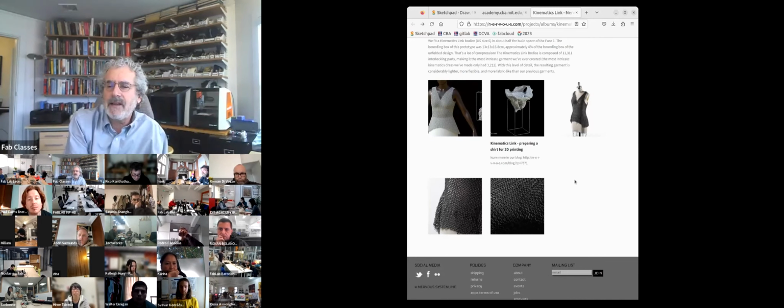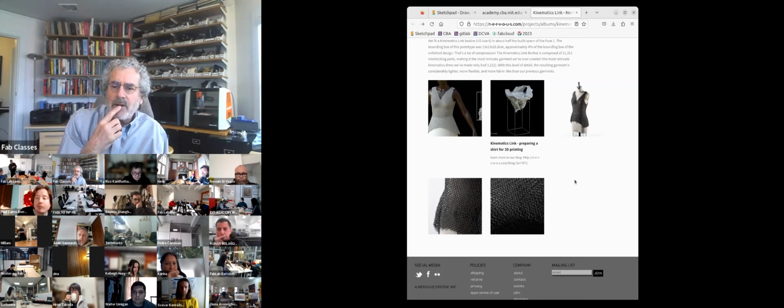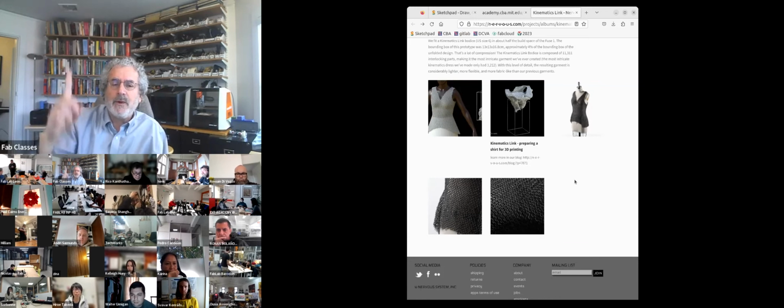Jason is asking about venting. Jason, this is similar to, it's not as bad as laser cutter venting, but it's in the same spirit as laser cutting venting. Again, there isn't quite as much volatile, but you don't want to vent it where people breathe it. So in research labs, you vent it to the roof with a high velocity fan shooting it up. Short of that, you want the vent away from where people can be breathing the exhaust.